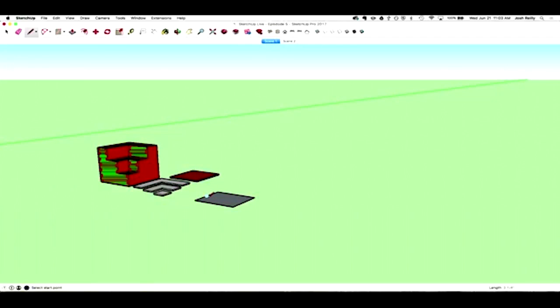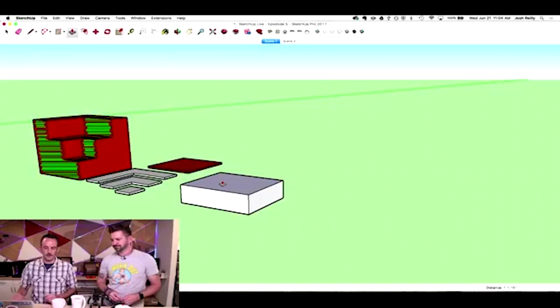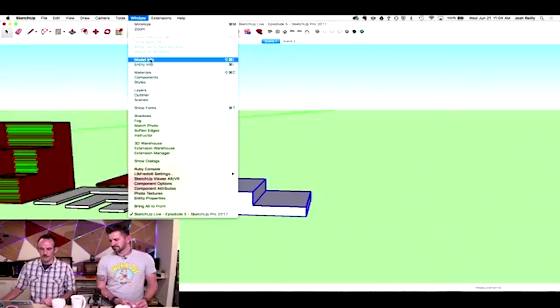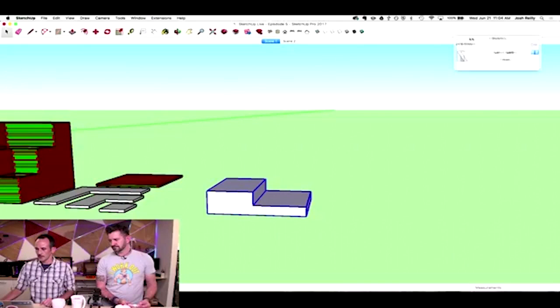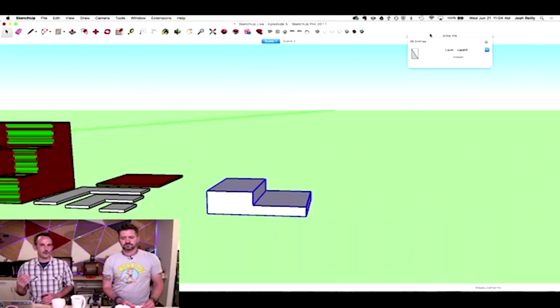So SketchUp is not a solid modeler, it's a surface modeler, which means there are some things we want to pay attention to make sure that our output from SketchUp is considered a solid. So you can see here, if I select all the geometry in this shape, and I'll open up the Entity Info panel here. You can see it tells me 26 entities. That's not so useful right now until we group this. So if we group this geometry, we'll have a little bit more useful information.